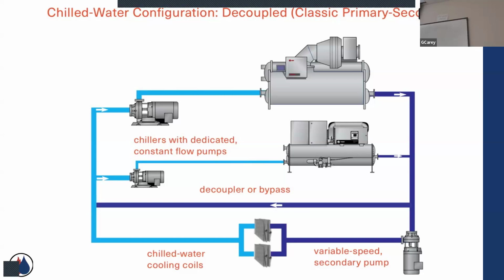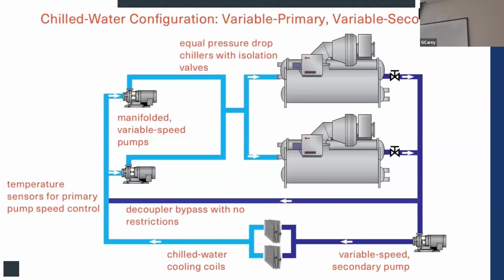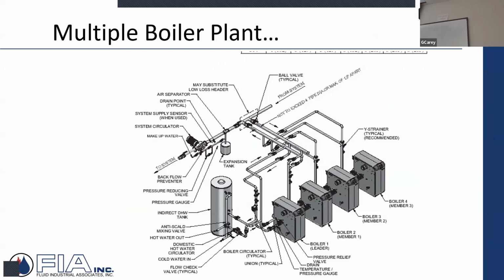So chiller pumps dedicated to each chiller, and then maybe going out to fan coils, a very simple drawing, but maybe a VFD variable speed pump going out to my chilled water coils, hundreds of them perhaps, in a complex. And then they had different variations, and they'd have control valves, so either pump could go through the particular chiller. They started getting into some pretty fancy sequences of operation and how they bring chillers on and off, etc. Same thing, whether it be chillers.